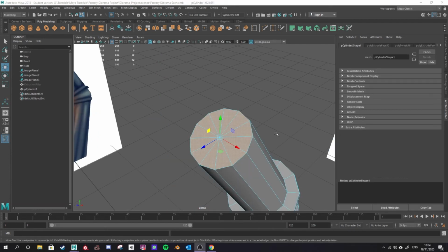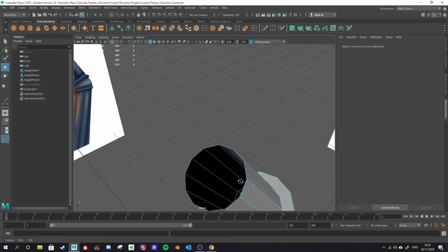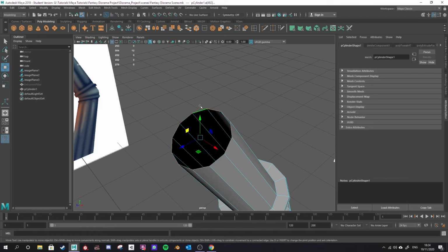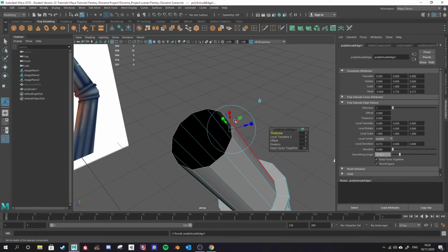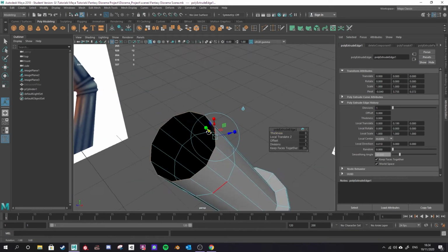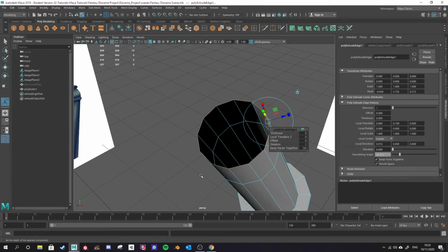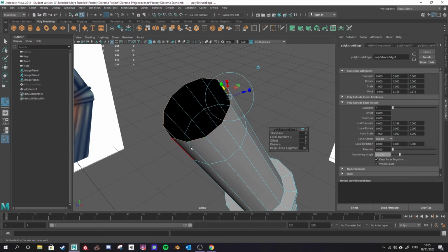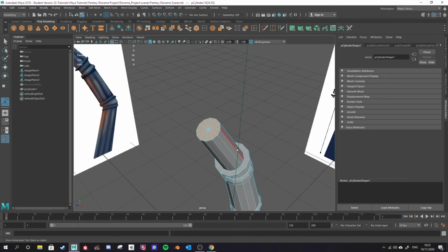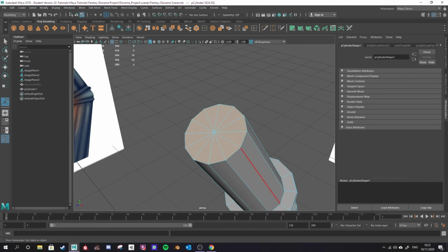The one exception to that rule would be if I delete these faces here so that I have an open face, so the edges aren't connected to anything. I can then use the extrude tool to extrude those edges out. That's fine. It's the only time you can use edge extrusion, when there's no geometry on the top or on the inside. So if you just have a hole that you're going to fill later on, that's okay. But whenever you have complete geometry like this, you never extrude the edges. It'll only cause you a headache later on.